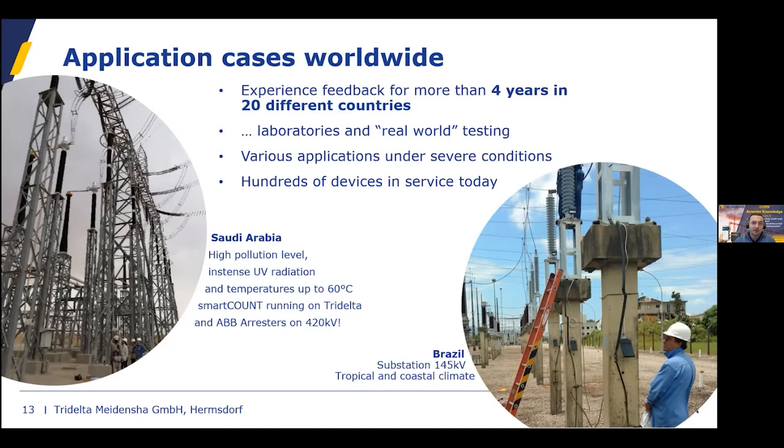So smartCOUNTs are running there on Tridelta arresters and other brands. It's quite interesting. The main purpose for the utility is to assess the contamination, so the external current on the surface of the insulators. That's the main motivation, but of course they have a complete assessment.